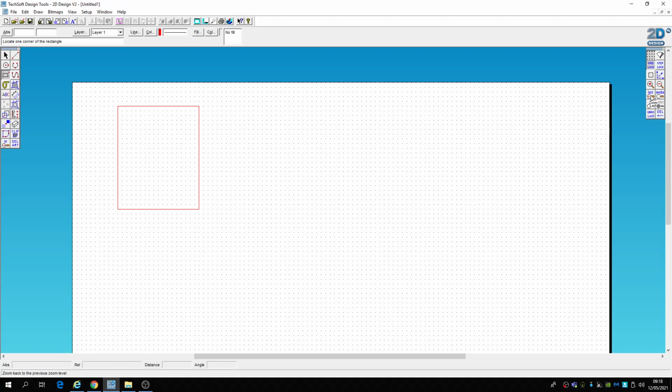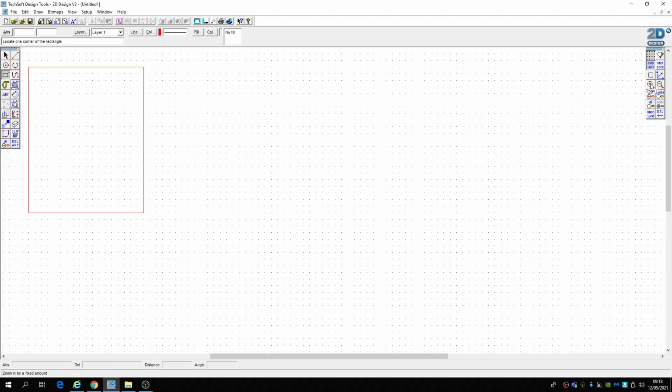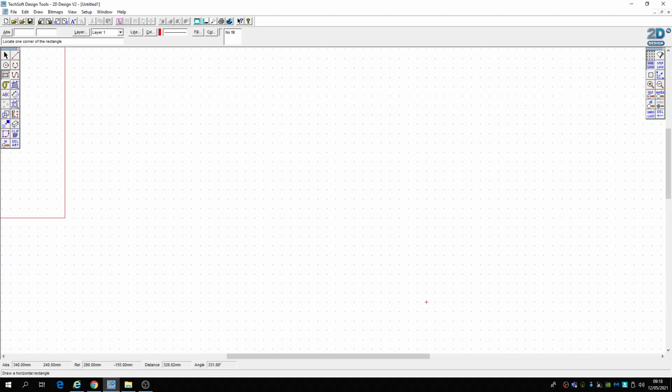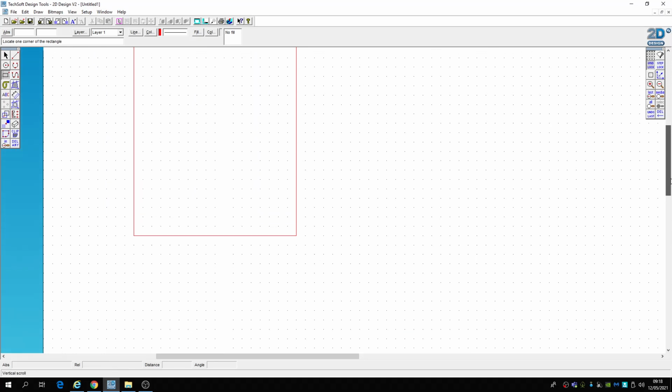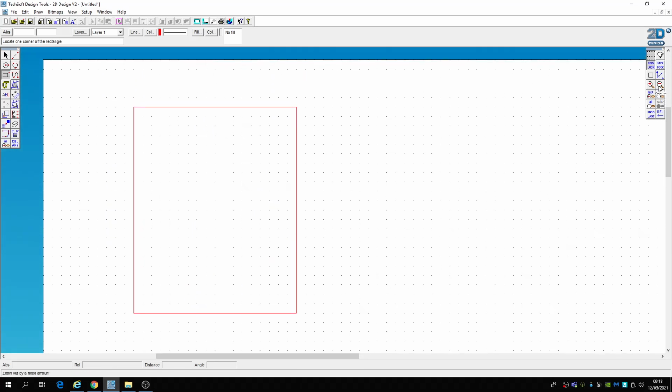So now what I'm going to do is pop over to the right and enlarge that page a bit, because that helps me with the next little bit that I want to do. I'm going to click on step lock, and go to the circles tool, and go 2 dots in and 2 dots down, and draw a 2mm hole.